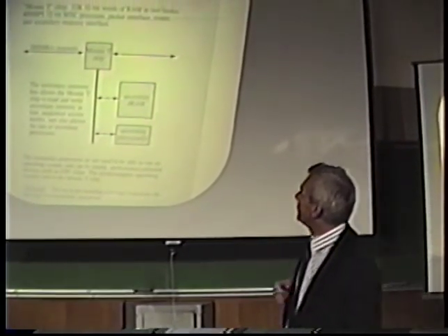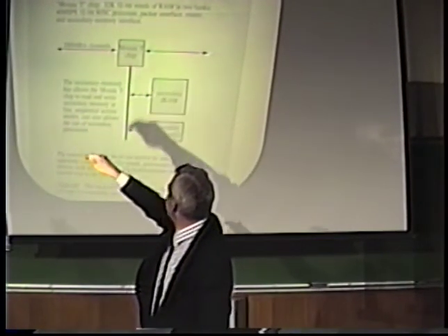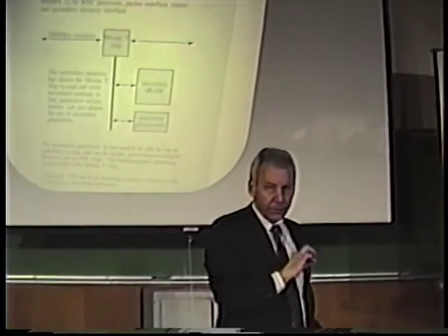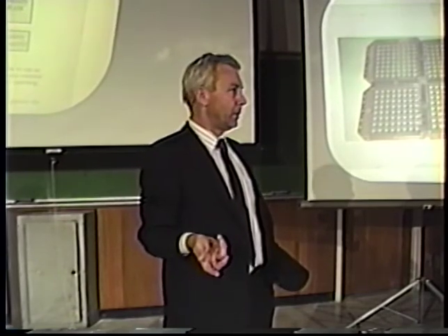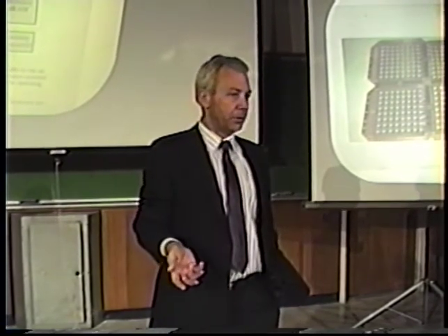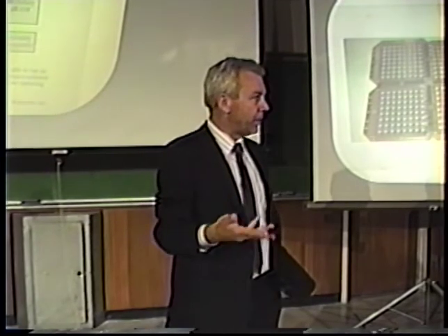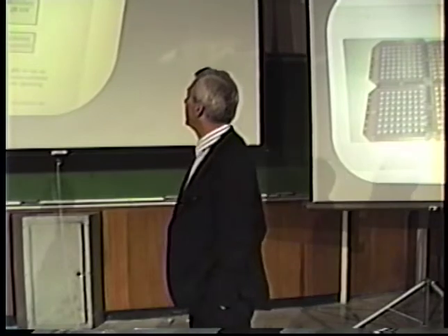One other difference is this chip has an interface to secondary memory. If you look at what one of these Mosaic chips costs versus what memory costs for your Macintosh, you're disappointed, because the memory for your Macintosh costs about 1/10 as much. So we obviously have to have some way of using commodity dynamic RAM memory. So we, of course, do this on some secondary bus.